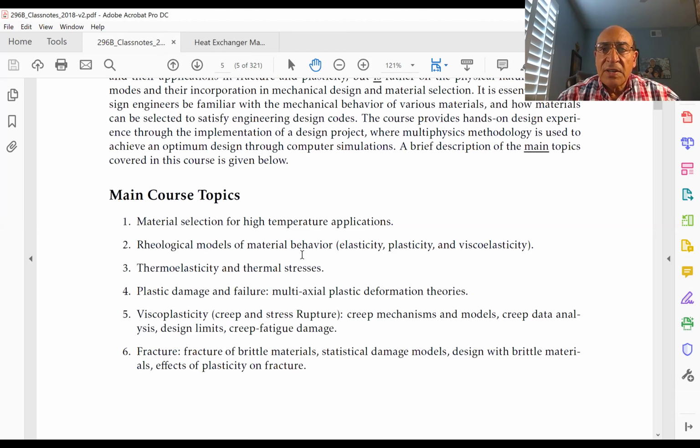These ideas will be a collection of elements like a mass, a spring, and a dashpot, the traditional elements that we used to have in physics, and we combine those to give us a simulation or a similarity to the complex material behavior that we would describe as stress-strain relationship or stress-strain time relationships that we use in finite element codes.